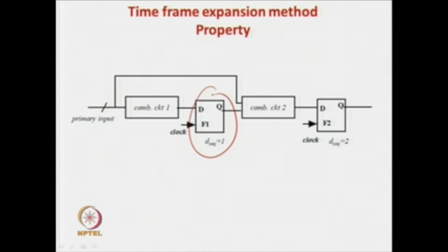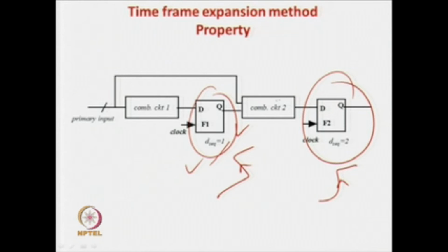This is the sequential circuit of depth 1. It is a combinational circuit. So, you apply a clock, and this is set. For depth 2, in depth 1, in the first clock pulse it has been set. Now, for depth 2, you require another clock pulse, because in the first phase all this is set, and in case of the flops with depth level 2, all the flip flops with depth 1 have already been set. So, just apply another clock pulse and this output will be controlled.